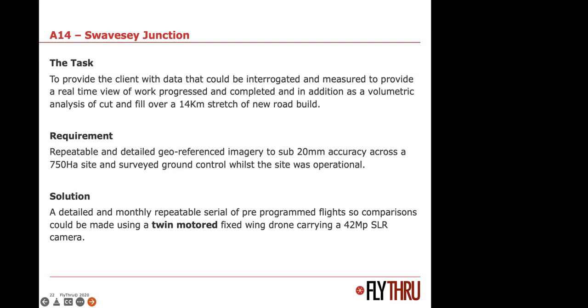We were able to, in the summer months, not winter, but the summer months, do this in a day and give them detail of the 750 hectare site, which they could then use to quantify the amount of muck that they would have to shift from one place to another. They estimated during the 2.5 years they were on site, they saved over £1 million just in higher cost of machinery and plant that they wouldn't have to use to move this vast quantities of material around.